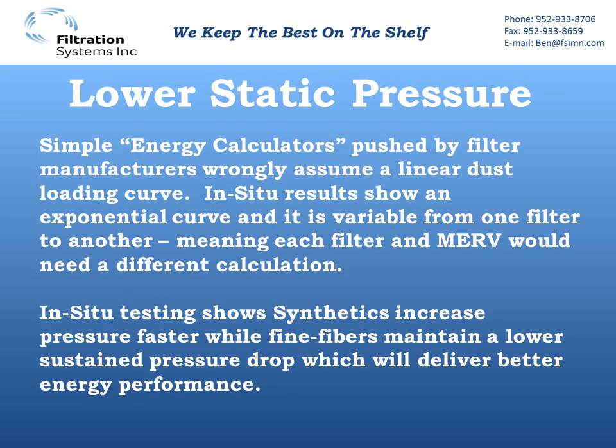The other wrong assumption that's often made is that the synthetics are going to last just as long as their fine fiber counterparts, meaning that the rate of increase in pressure drop is going to be the same between a synthetic and a fine fiber media. And again, in situ testing has proven ever since these have been out that that doesn't happen either.